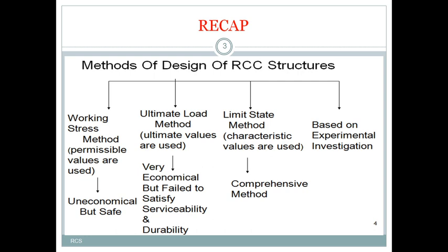Then next, coming to the ultimate load method, this is based on ultimate load values. These ultimate load values are calculated by enhancing the values of working loads. That means the ultimate load can be calculated by multiplying the working load with some load factor. That is called ultimate load. The elements designed by using this ultimate load method are very economical, but they fail to satisfy the serviceability and durability requirements. Why?